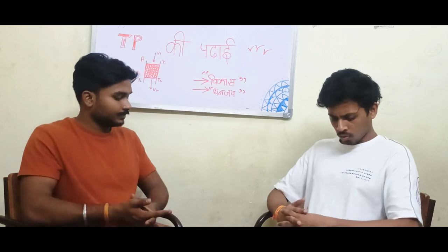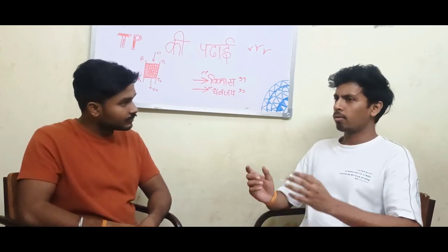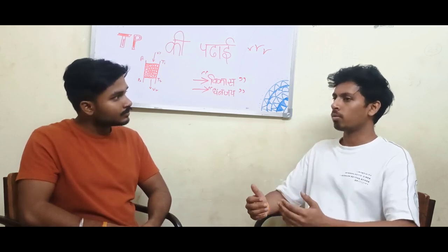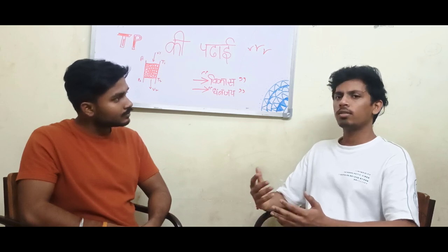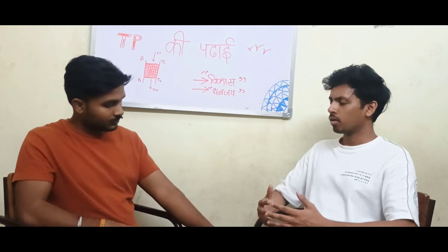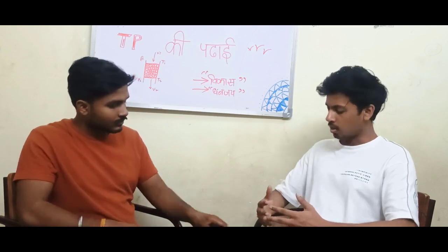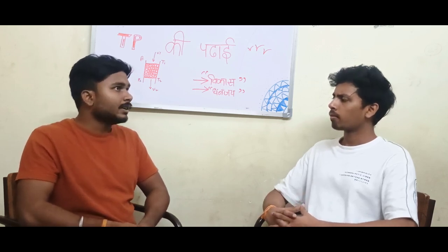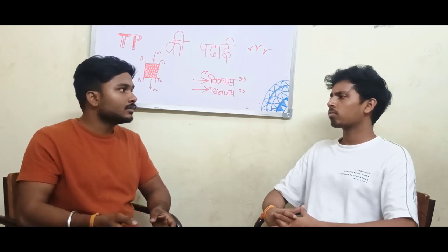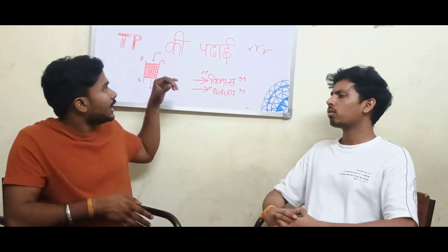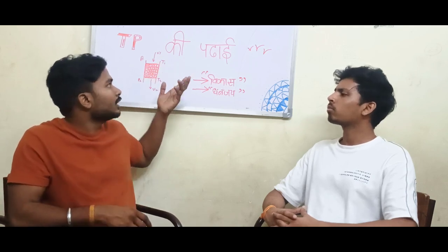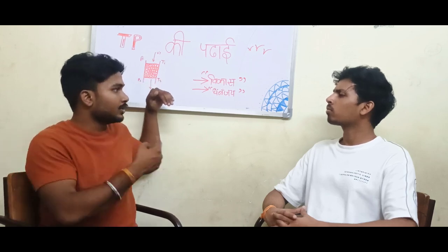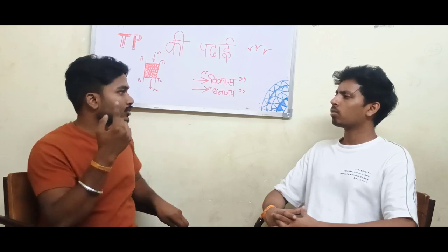Suppose we are measuring through experiments and finding the mass transfer coefficient. What are the challenges in measuring the mass transfer coefficient in a packed bed column? If you are doing it experimentally, it is quite tough compared to theoretically, because in the column, the fluid coming from inside might have maldistribution, that is, the fluid is not evenly distributed.